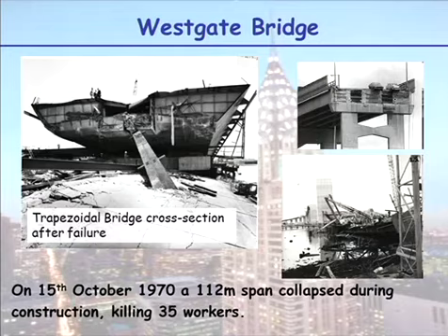Kentledge is basically dead weight. What they did was they put 10 concrete blocks. They said, bring out the blocks, 8 tonne each. So they loaded one side to lower it. That's what you do. That's what they did. There's a discrepancy. It's harder to lift up. You're up in the air. You load the other side a little bit more. And that's the way they constructed, and it was all very well and good. It was because it was this new plate girder design. So each one of these tonnes deflected it downwards.